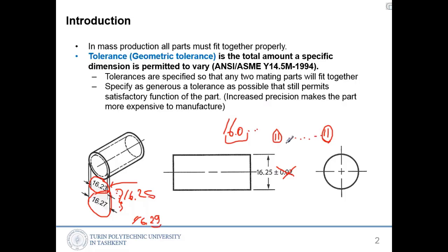So then you will select a measurement, a measuring device, and based on this you will select the manufacturing tool or machine. Then you are producing, and checking with your measurement. If it is inside of this range, you accept it and assemble it. What's outside of this, you have to repair or recycle, until you get the value inside. So that's the meaning of the tolerance.